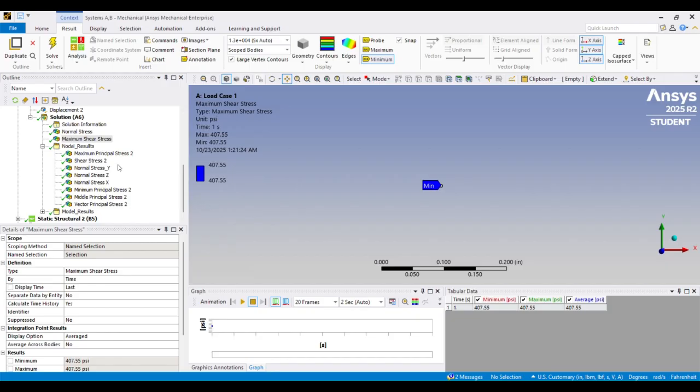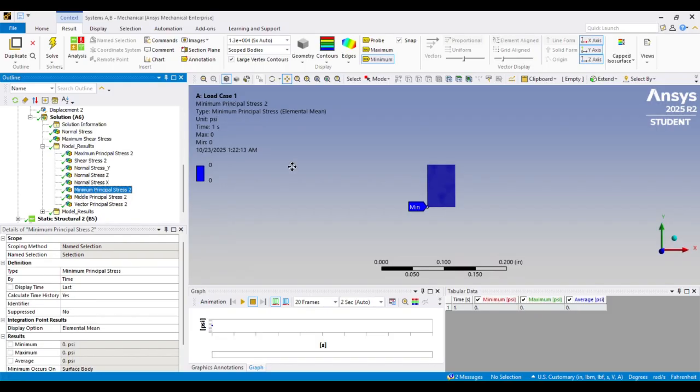And again, if we look at the model, we see that the max principal stress from the model is 815.1 and the minimum principal stress is 12.785. In the 2D case, what they're calling the middle would be the minimum. And you can see here that this other principal stress is 0, which we would expect.